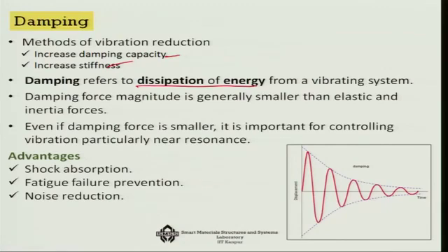So, the damping study is very important, and that helps in terms of shock absorption, fatigue failure prevention, noise reduction, etc. So, this is typically an under damped curve, as you can see, under viscous damping, and you can see that the response is coming down exponentially. As the damping increases, this will be more and more, and there is something we call the settling time. That means, when the initial amplitude comes down to within say 2 to 5% of its initial value, we say that the vibration has damped down.